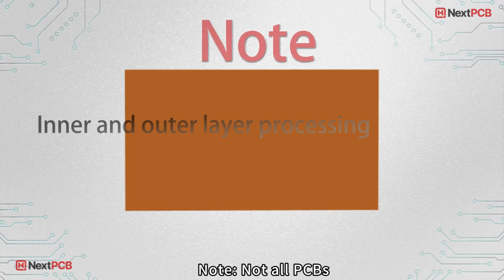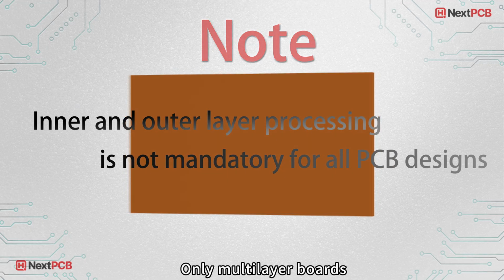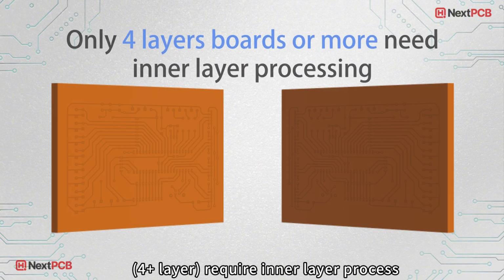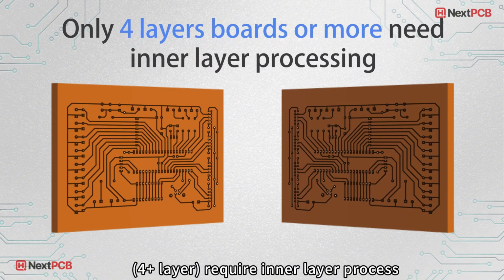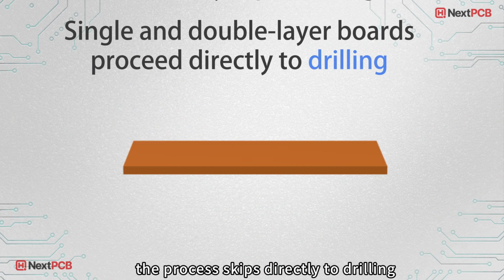Note, not all PCBs require separate inner and outer layer processes. Only multi-layer boards, four plus layers, require the inner layer process. For single/double layer boards, the process skips directly to drilling.